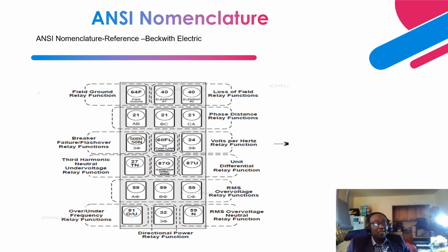If there's a breaker failure, let's say a relay sets an output and it's supposed to trip the unit breaker and it fails, then after a period of time, this relay senses that there is still current flowing through the breaker, and from there it starts a timer to trip other breakers that are in close proximity to the unit breaker that was supposed to be tripped.